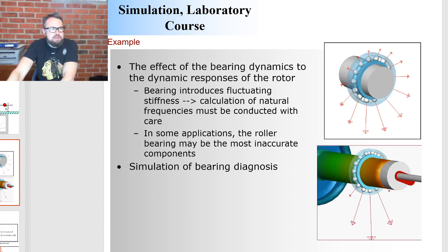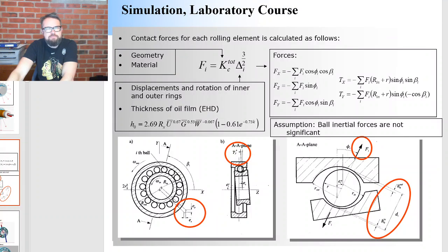Of course there are quite a few details, but roughly speaking this shows how a penalty force is computed. We have stiffness coming from the material parameters, then penetration coming from the geometrical computation, and then we have n, which in this particular case is 1.5, and it corresponds well to the situation in ball bearings.